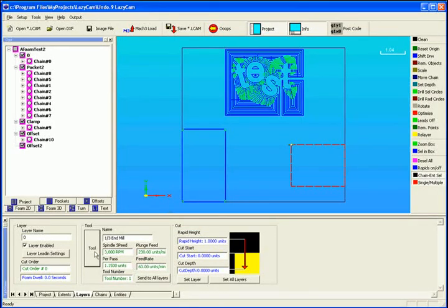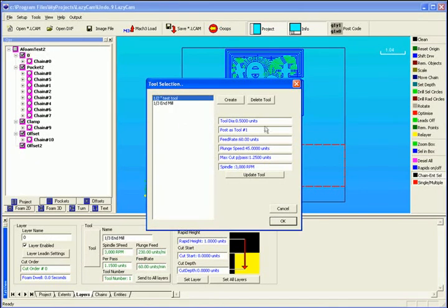The reason we attached it to tools is the tool really controls all of these items. As you can see, the diameter of the tool is set, as well as the posting number. This is because you may have 10 tools in the tool cabinet, but only 3 tools on your mill, because you're reusing 3 of the tools here. For example, you could enter a half-inch tool 3 times. Once a half-inch tool for cutting aluminum, one as a half-inch tool for cutting wood, and another as a half-inch tool for cutting foam.